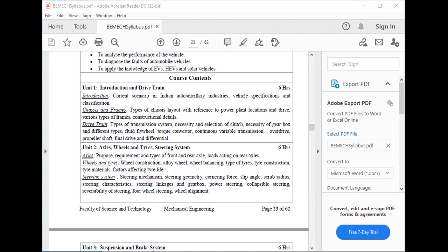So it is pulled back by the release levers against the compression spring so that the friction linings on the clutch plate are free of flywheel and pressure plate. The flywheel rotates without driving the clutch plate and hence the shaft. When the pressure of the thrust race is released, the compression springs are free to move the pressure plate to the left, bringing it in contact with the clutch plate.